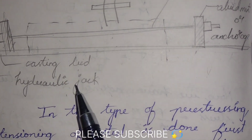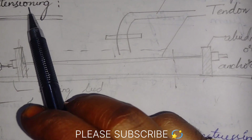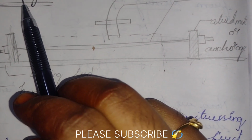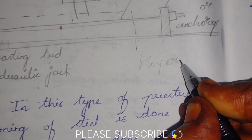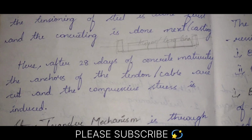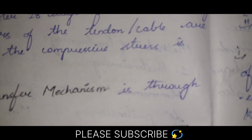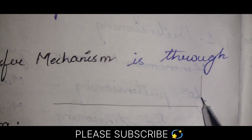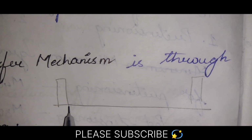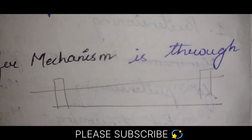So we are now studying the systems of pre-stressing. First comes the pre-tensioning system. In pre-tensioning there is only one system, that is Hoyer. In this anchor system, a single bed is taken. In the single bed, two anchorages are provided. These are the two bulkheads. To these two bulkheads, the tendons are first anchored.